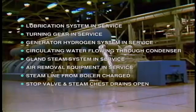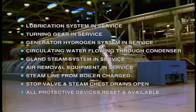Stop valve drains and steam chest drains open to ensure removal of any water, that is, condensate, and all protective devices reset and available.